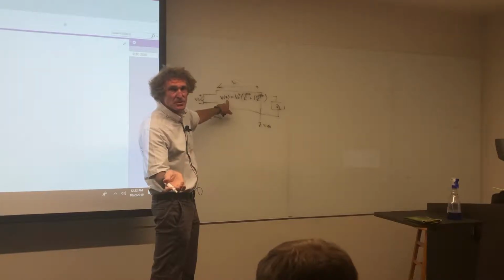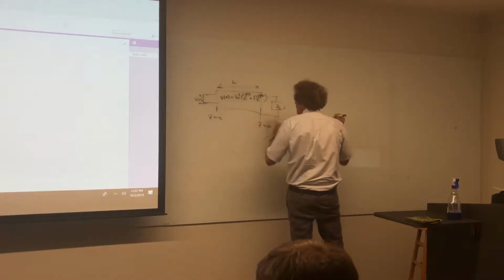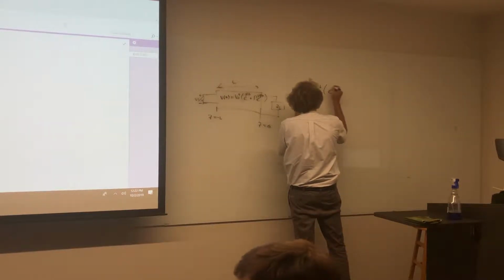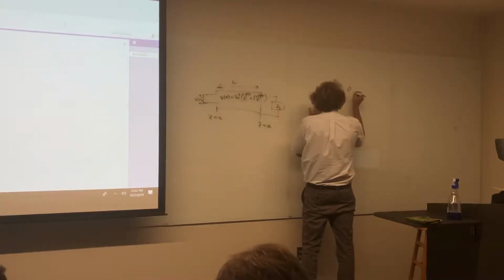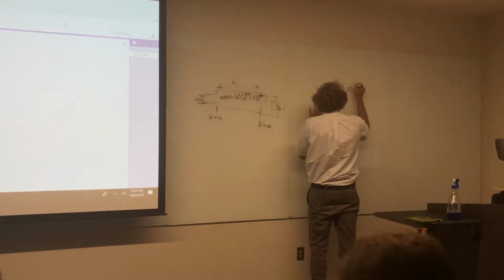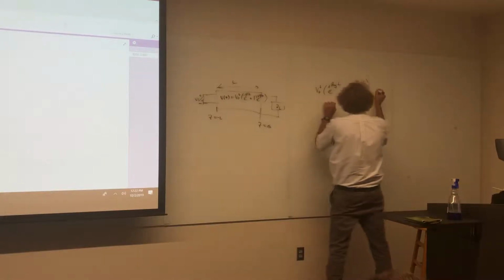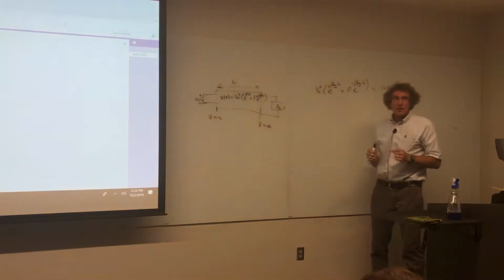No source resistance, so you don't have a problem, right? That means if I want V0 plus, I can say V0 plus times e to the plus j beta in the guide times L, plus the reflection coefficient times e to the minus j beta in the guide times L, is equal to 100 volts. And then you solve for V0 plus. Do you all follow me on this?